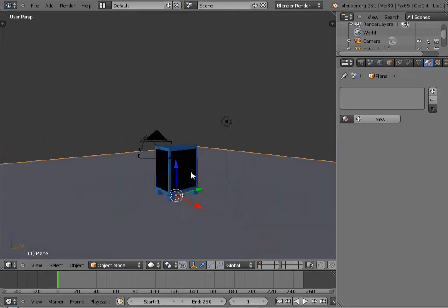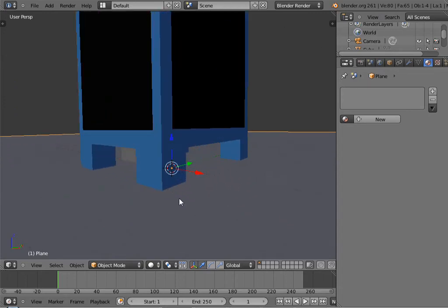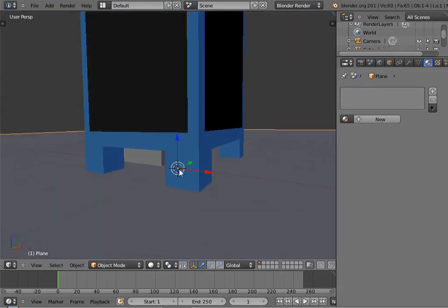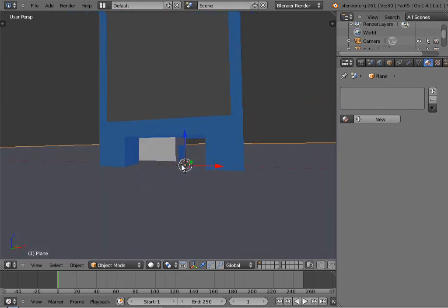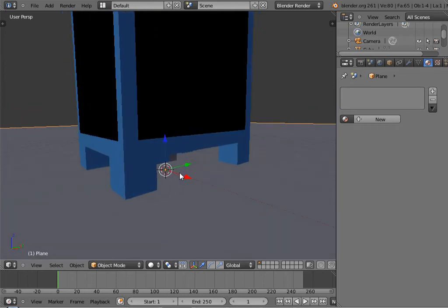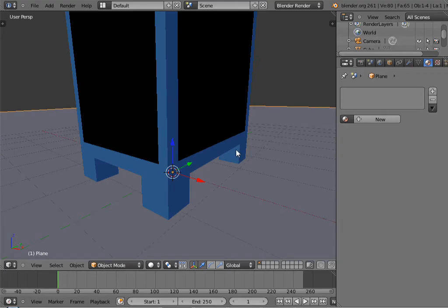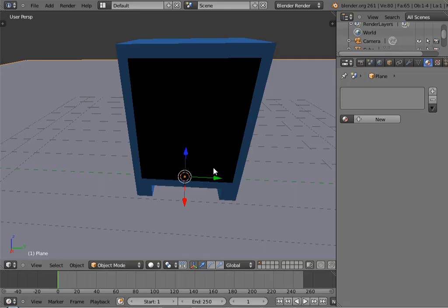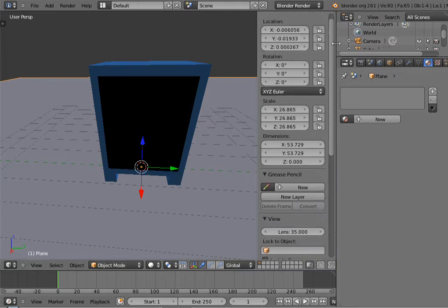But this is good enough just to show off, and it's automatically been placed, because the 3D cursor is still at this 0 point. I think I managed to move it back fairly accurately. It's right in sync with this virtual grid plane here. But if we want to take a proper look at its exact location, we can press N to bring up this thing here, drag up here, and we can see its X, Y, and Z location in numerical value.